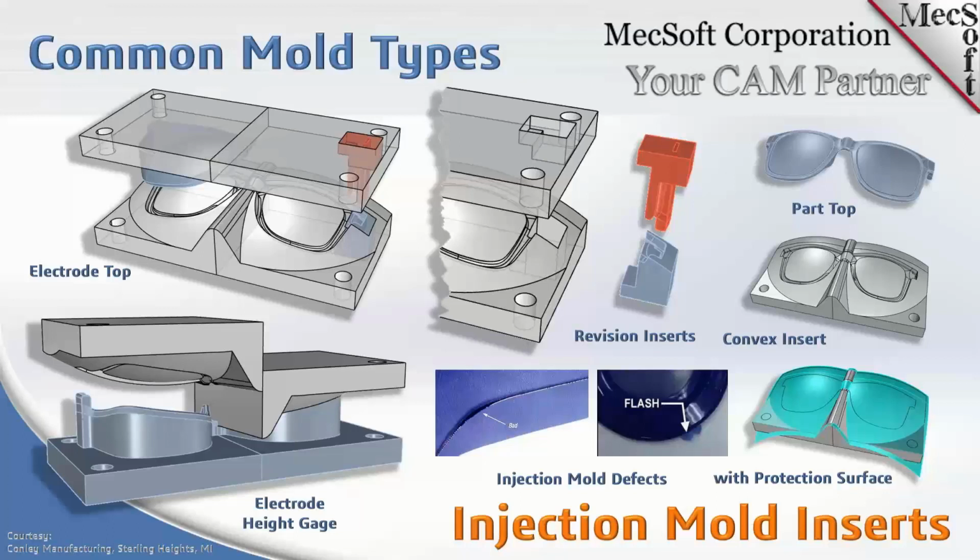Or more precisely, they can cut holes in that insert using a wire EDM machine to get a precise insert measurement, where you can redesign an insert to go in the insert, which contains the revision. So this is primarily the reason why precision is the utmost concern in plastic injection molds.